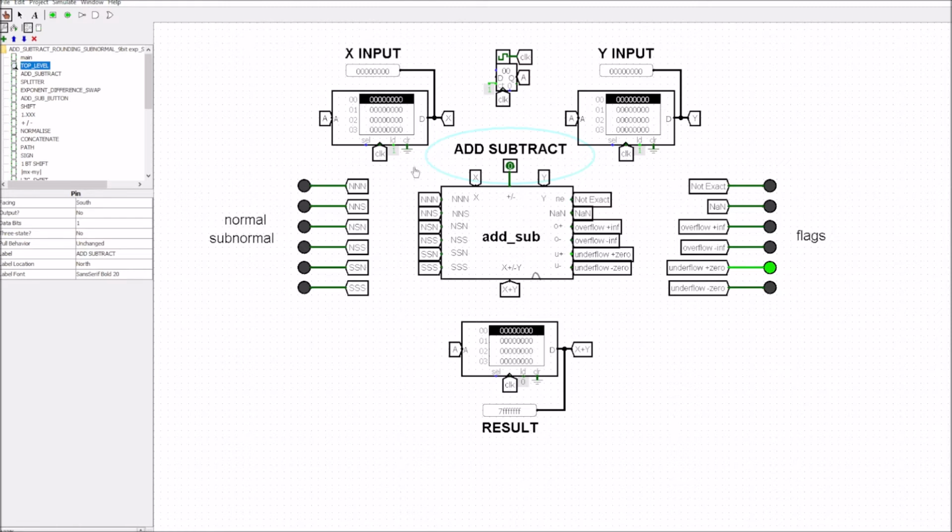So don't worry if you're looking at these blocks and you don't understand what they are. They will be explained thoroughly in the rest of the course. But let's just go ahead and we'll put in a couple of numbers. But before we know what numbers we're going to put in, we're going to have to convert the numbers to hexadecimal. We don't want to continually put in 32-bit numbers, so we would have 32 ones and zeros. That would just be really annoying. So what we're going to do is put the number format in hexadecimal.